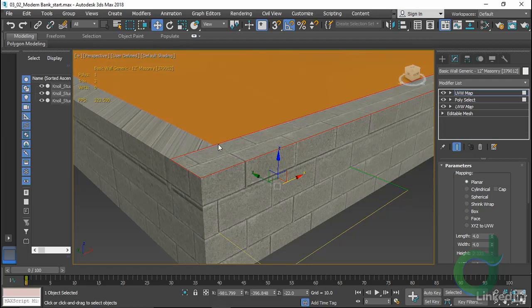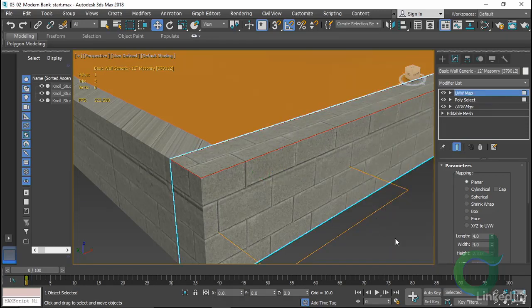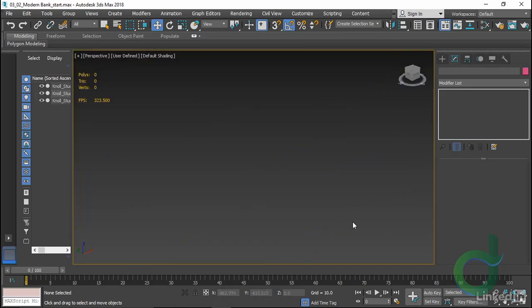We can definitely see we need a little either mesh surgery or another material here, but we can do the same on the top face of the other one, and it'll look pretty good, as if somebody considered at least having top and corner blocks to use on this wall. When you're done, you can right-click and choose Top Level and deselect and check it out.